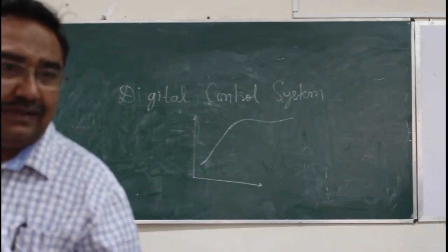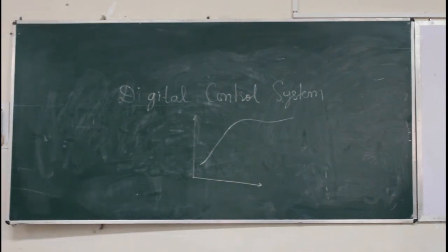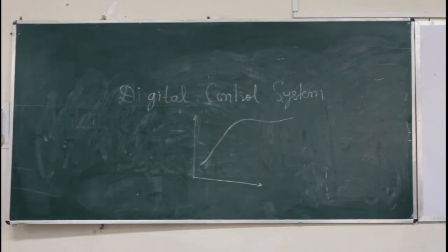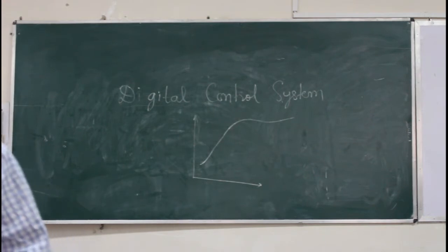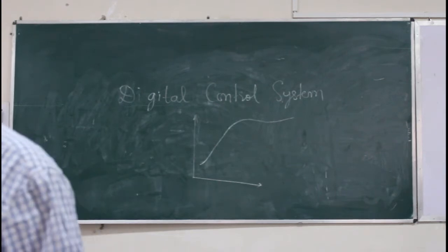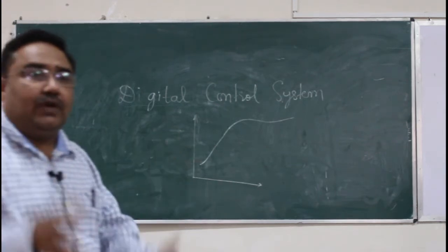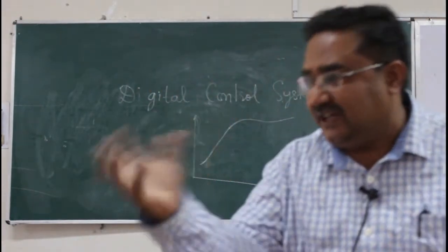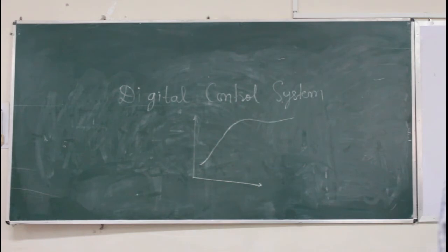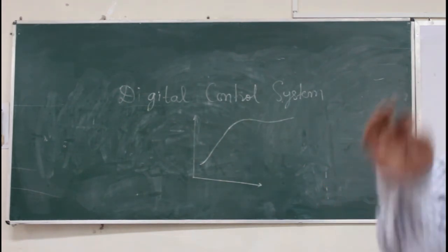A motor. To this motor, a blade has been connected. So when you give supply to that motor, the motor will rotate, and the blade will also rotate, and whatever material is present near that blade, it will cut and crush it. It is rotating at such a high speed that within a few seconds or minutes, the raw material, that is limestone or whatever is being put in, is crushed. Is it clear? That is why it is known as a crusher. And the basic part is the motor. So what supply are you giving?